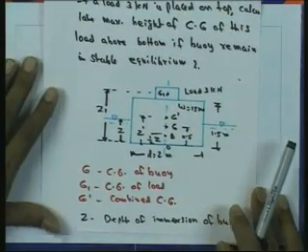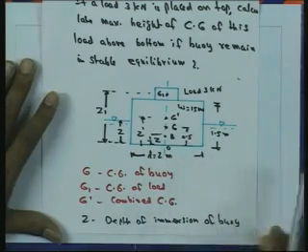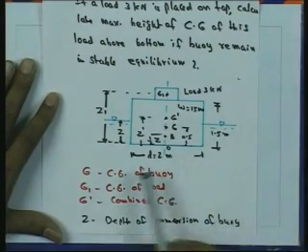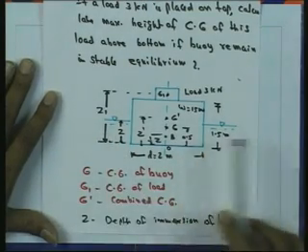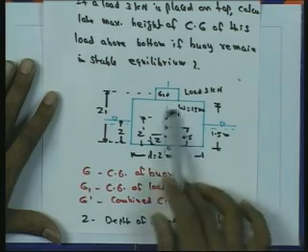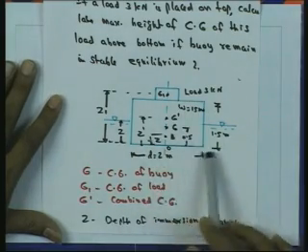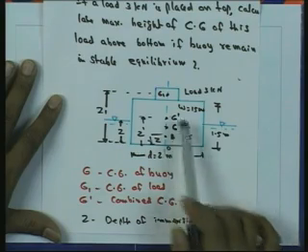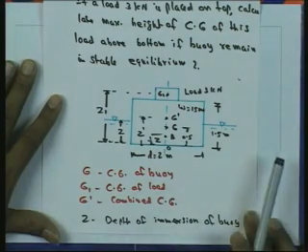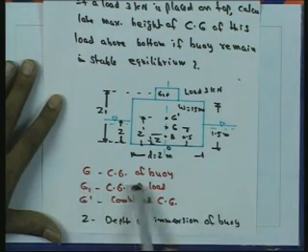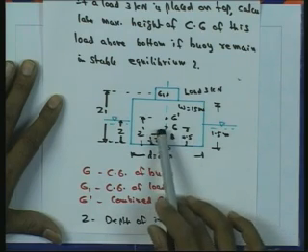So we want to determine the new position of the center of gravity. All the problem dimensions and loads are given: the buoy weight is 15 kilonewton and the newly placed load is 3 kilonewton. Here, let G be the center of gravity of the buoy as shown.